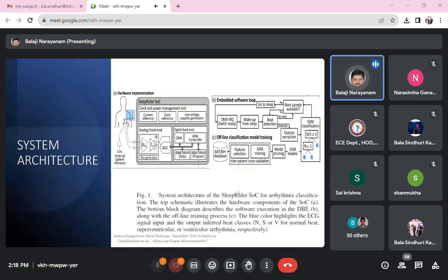It is a block diagram level entry, which I can use to make my System Generator model, simulate, then synthesize, and I can program my FPGA with a .bit file or a .hex file. That makes my implementation much easier, so I need not struggle with either Verilog HDL coding or VHDL coding. System Generator is an easily available option, so you may try that.